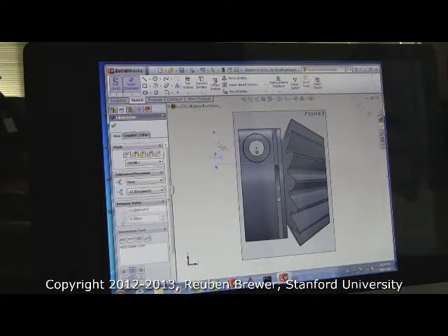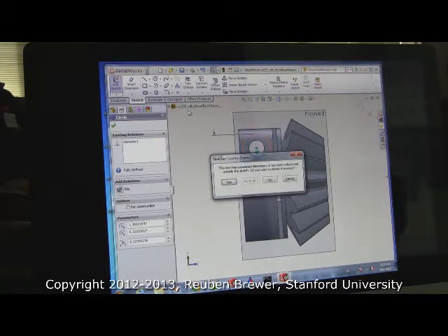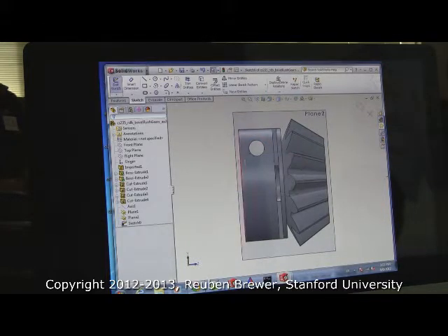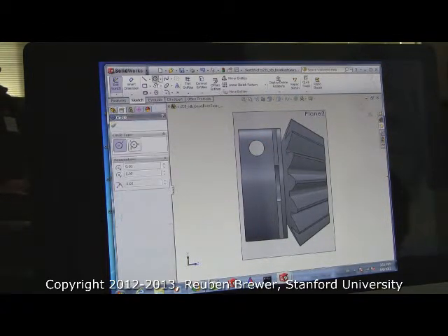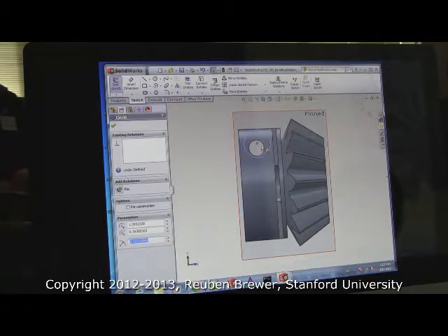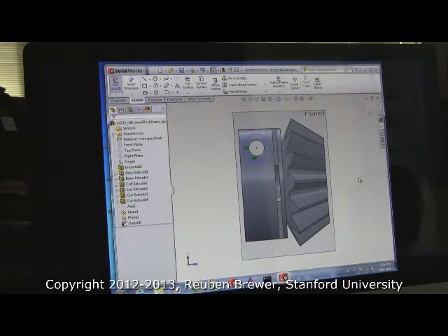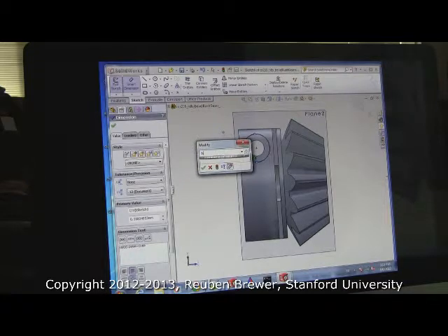Okay, well let me show you a trick. Everybody watch my screen for a sec. Say Solidworks is just being difficult, and it will not snap to, and I make my circle here. See how that's off center? I can force it to snap to. I press this circle, control this circle, hit concentric, boom. Okay, now smart dimension that to 6.5 millimeters.